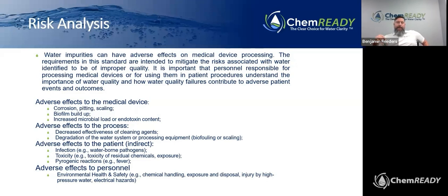And some of those adverse effects to the medical devices and the process itself could include corrosion, pitting, and scaling. Could have biofilm buildup, increased microbial load or endotoxin content. It can also have adverse effects to the process. So decreased effectiveness of cleaning agents, degradation of the water system itself or the processing from biofouling or scaling.